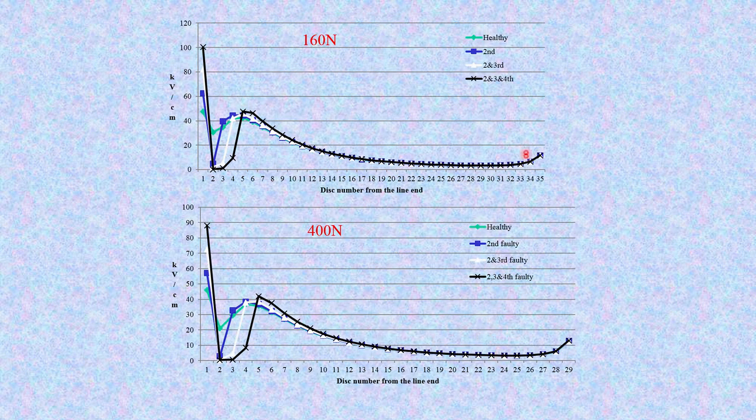For different discs, this is for a 765 kV or ultra high voltage transmission tower. What happens in case the faults are at different junctions, considering the fault at the second insulator, or a fault at a different location arbitrarily? We have tried to see how much potential or field modification happens. This gives an idea that in case there is a fault at that location, the adjacent insulator sees a higher potential or a higher field, which could be estimated to see whether it is reaching its dangerous limits, so that immediate change is required or it could be allowed for some more time.